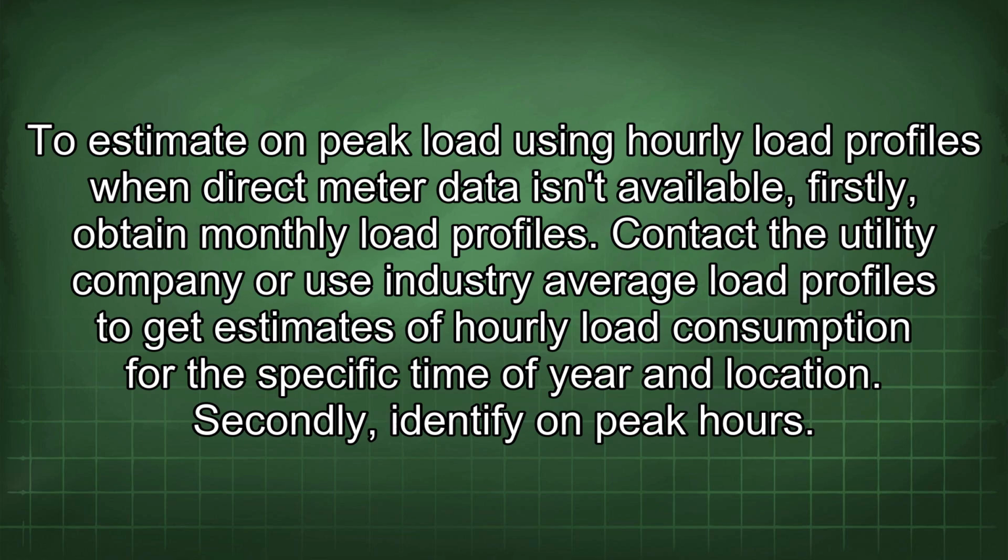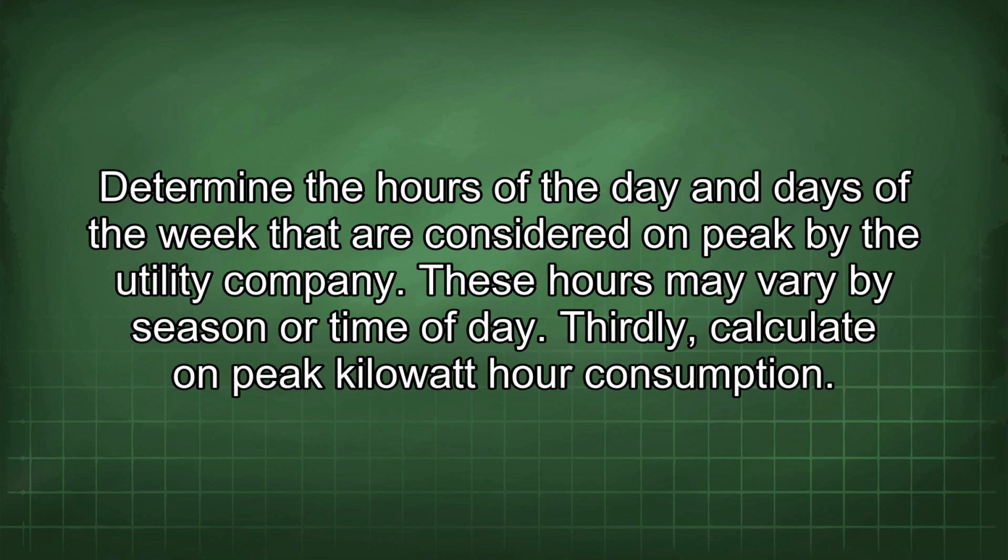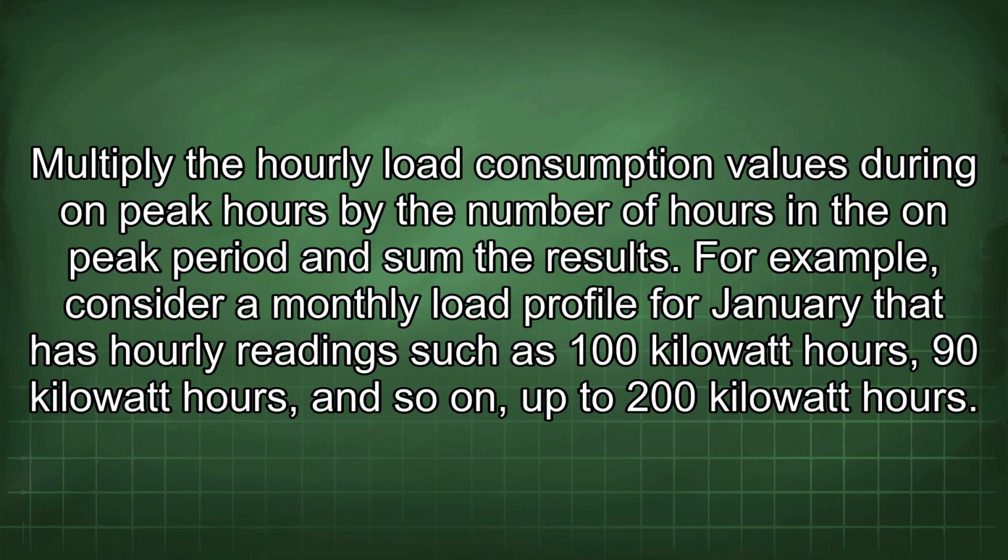Secondly, identify on-peak hours. Determine the hours of the day and days of the week that are considered on-peak by the utility company. These hours may vary by season or time of day. Thirdly, calculate on-peak kilowatt-hour consumption. Multiply the hourly load consumption values during on-peak hours by the number of hours in the on-peak period and sum